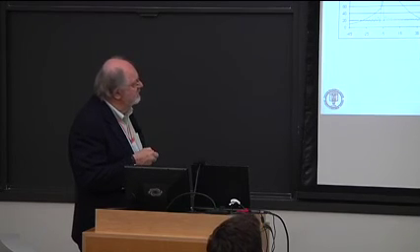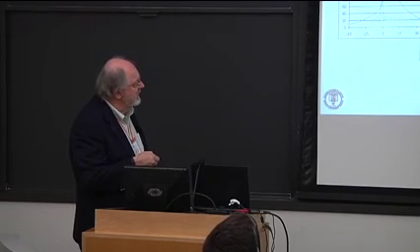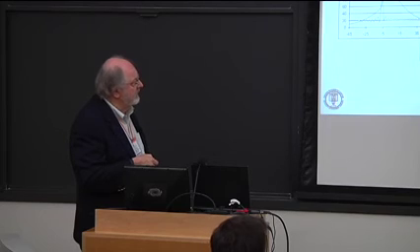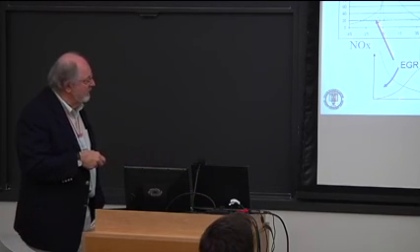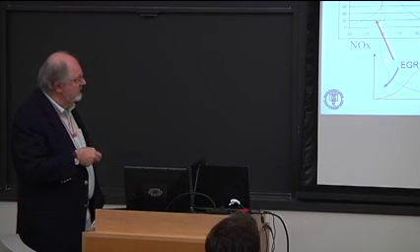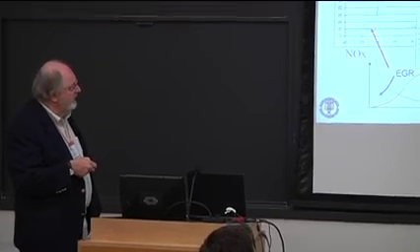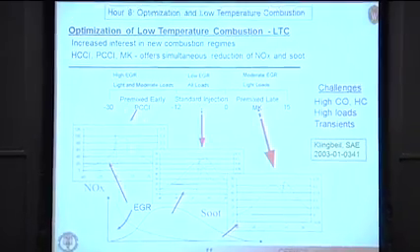Here's standard injection between 12 and top dead center. This is standard diesel. It's characterized by, let me show you this, high soot, whereas for the early injection case, low soot. The early injection case, on the other hand, has high NOx, but because we use high EGR, we can bring